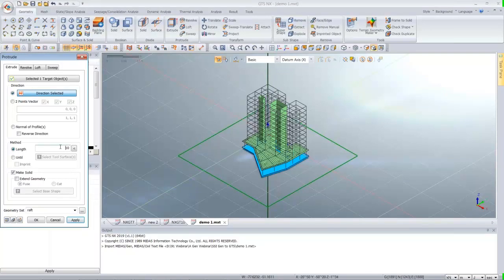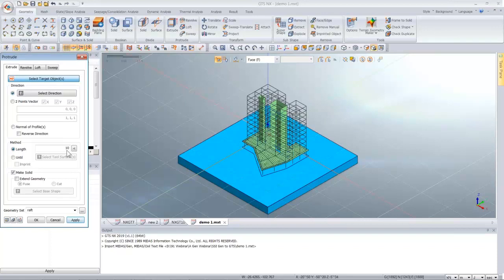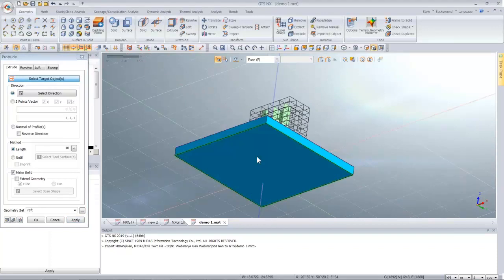And then by pressing the scroll button, I can select the bottom face of the soil, then select the target as the vertical axis and provide a length of -25, and that will actually be my layer 2. And then I'll click on OK.